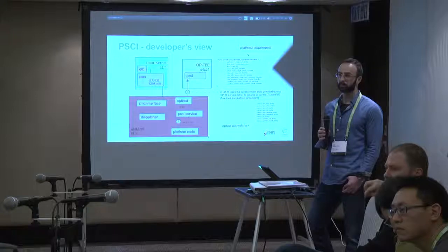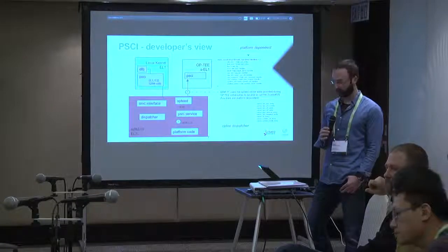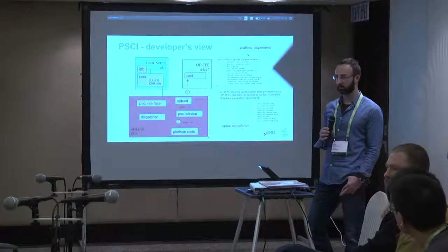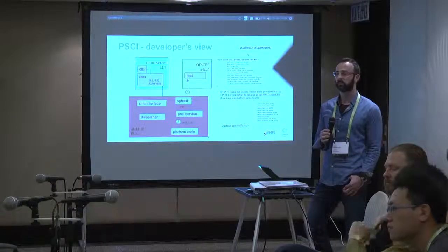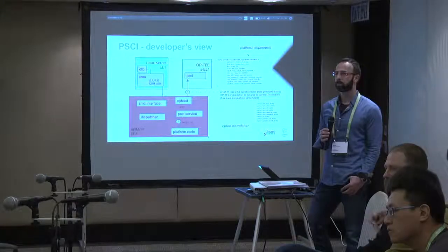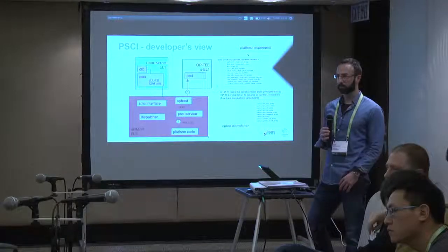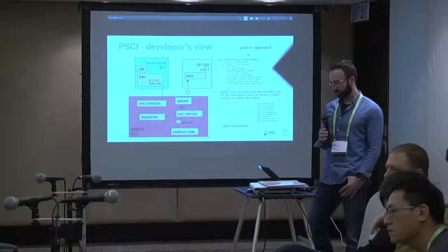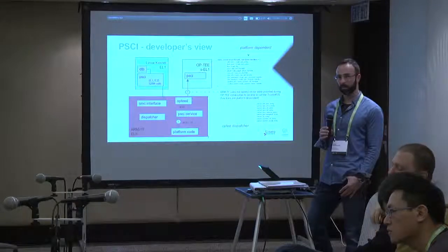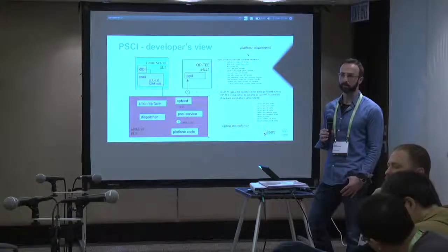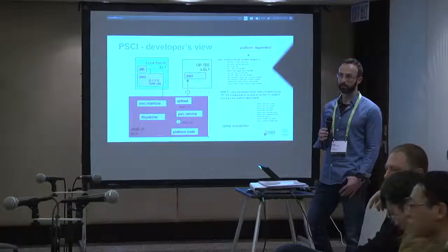You can't stop idling that core, but you can stop it from being CPU offed or plugged off. But we've only just added the wiring up of migrate within PSCI because we haven't had anyone from the Trusted OS community saying that they needed it. So at the moment, most of the Trusted OSs have either solved it themselves or appear to be MP, even if they only run on one core at any one time. Which means they're going to have to do something like the CPU idle coupled state, which essentially has to wait for the other cores to idle before they can idle that main core.